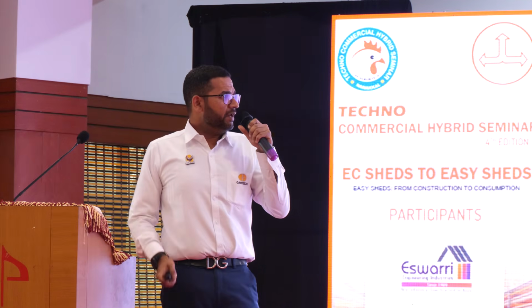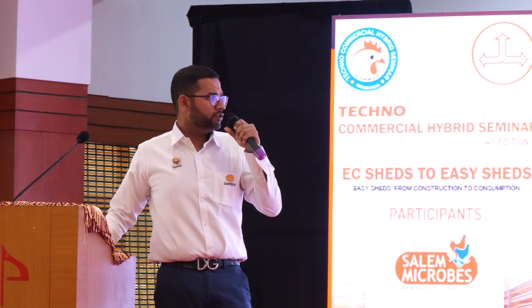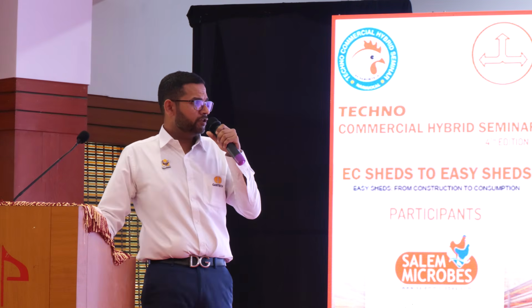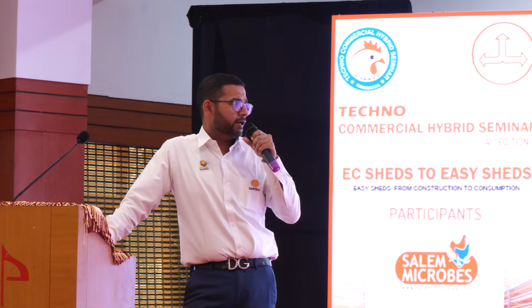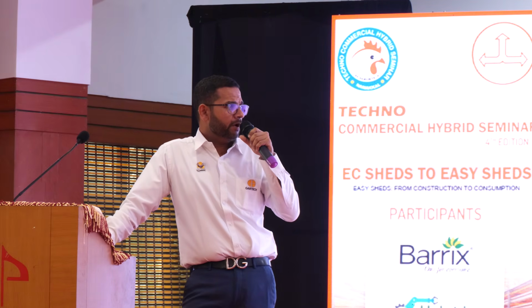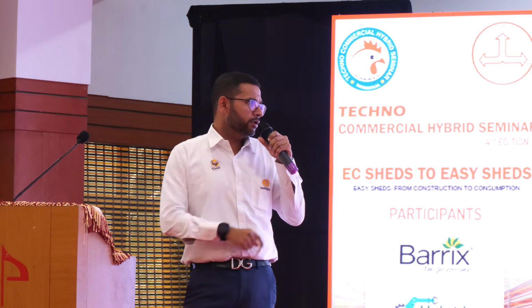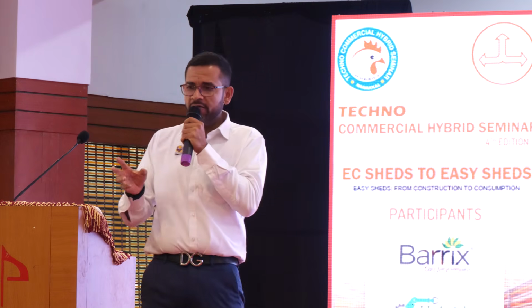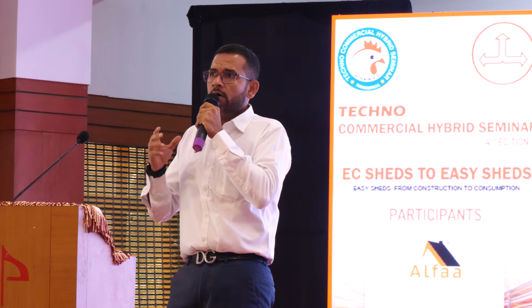Ventilation air exchange is used to remove moisture produced within the building. Excessive air exchange can remove too much moisture and produce dry and dusty conditions. A well-designed and insulated house with proper ventilation equipment and controls will work around the clock to achieve the desired thermoneutral zone. See, this point is very important, because what it is effectively trying to say is, earlier what I